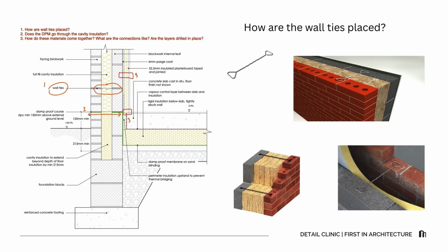So let's answer the exact questions raised on the student sheet so nothing's left hanging. How are the wall ties placed? The wall ties are set out in a staggered pattern as the wall rises, with the drip centred in the cavity. Spacing follows the project specification and exposure category. The key principle is that the ties connect the leaves without creating moisture bridges inwards.